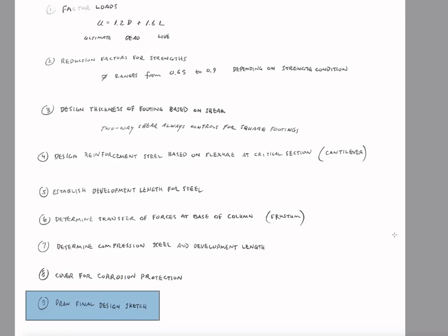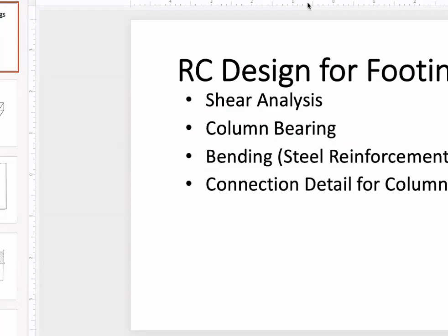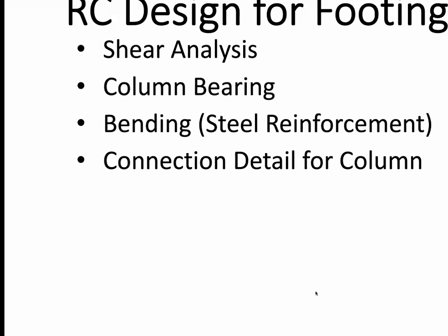And I'd like to look first at that PowerPoint. So this is the reinforced concrete design for footings, and I would like to share with you the steps again, but this is a refined version, not getting down to the nitty-gritty of factoring loads and so on, but hitting the main components of shear, column bearing, bending, and connection detail.